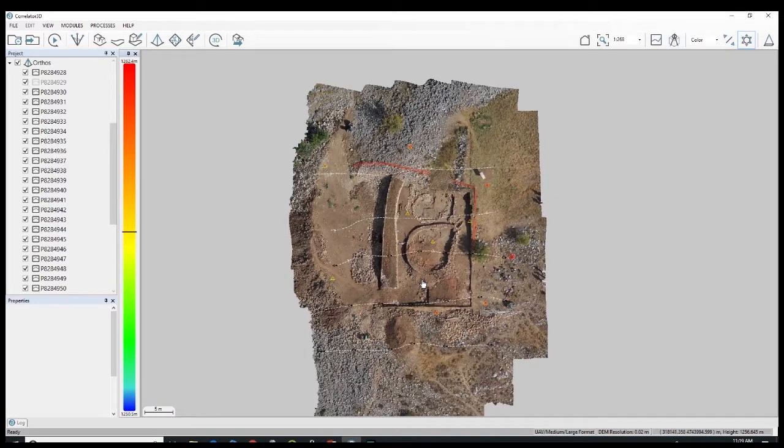There's a last thing I would like to mention about creating the mosaics. There's a color balance process that is done. So the software is going to put different sample points all over a mosaic, and will use these samples to calculate different statistics, with the goal to do a color adjustment on the different single ortho in order to create a color balance mosaic.